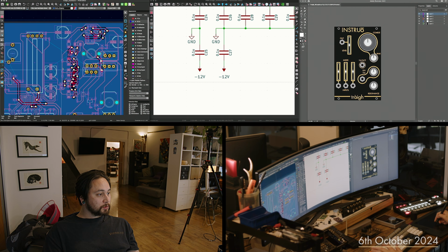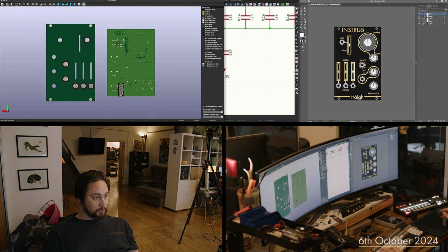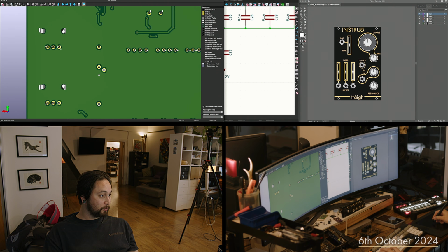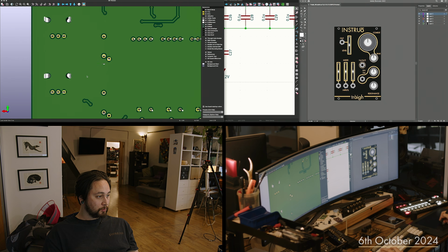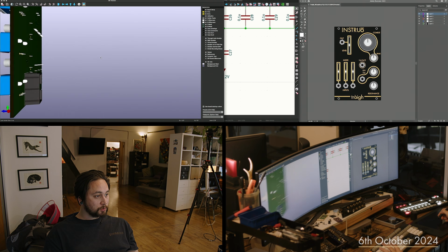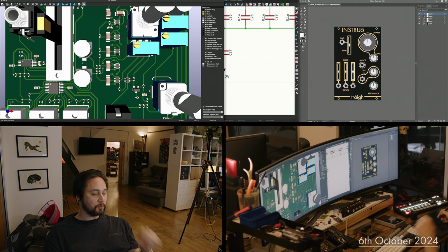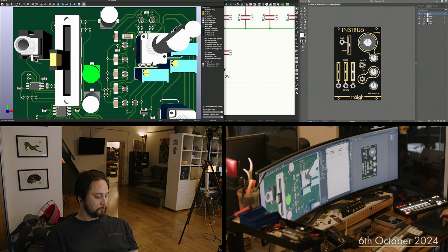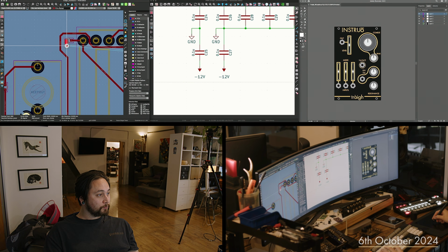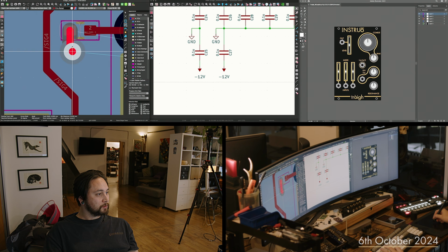And here we can see we've got a solid copper plane on the bottom. See that there? So any remaining air wires to be connected. You can see any of the existing ground pads, it's added the thermal spokes around it all, like that. So it just means on the top layer I need to find every ground connection and then punch a via through to make connection with that bottom plane. So just work through that. I can set this to being net class.